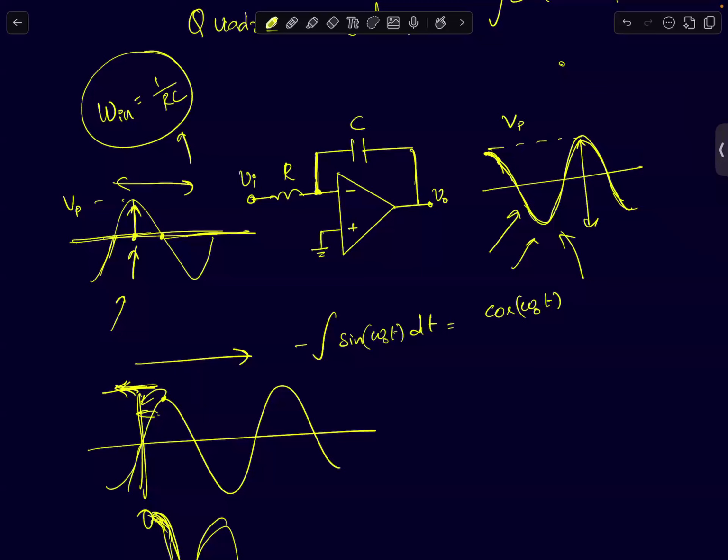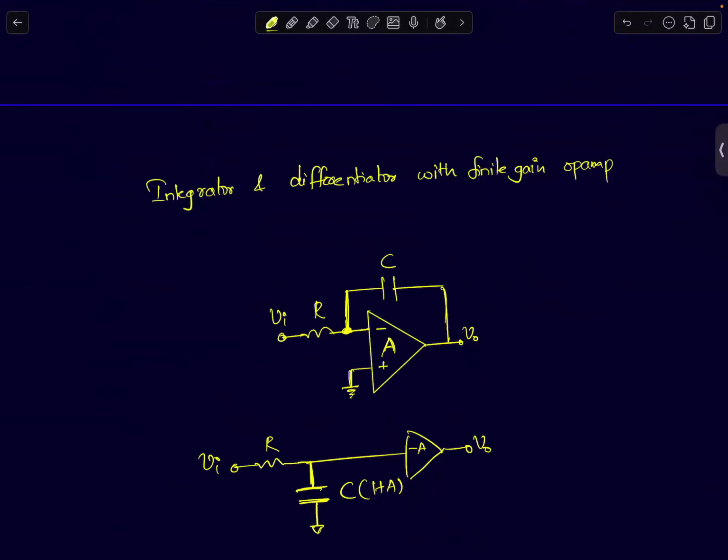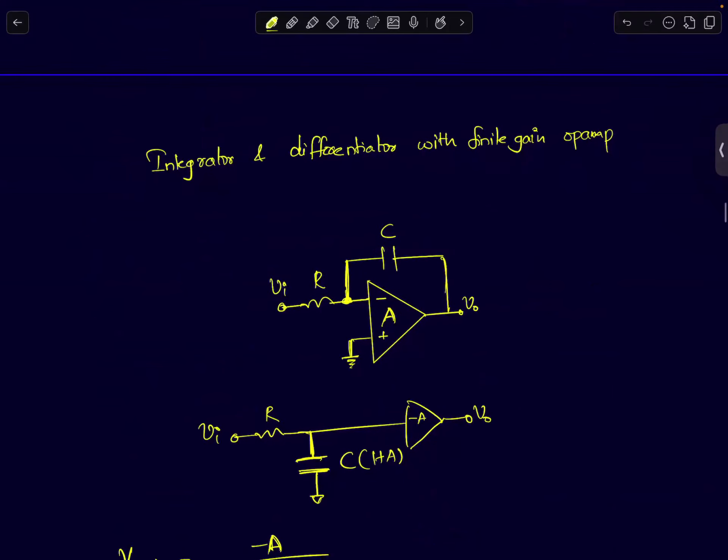The systems that we use today operate at much higher frequencies, so an op-amp circuit may not work, but the idea is somewhat like that. You can think of it like that. So if I feed it a sinusoid, I'm going to get a cosine waveform. And at a later time in the course, we will see that there are such circuits called quadrature oscillators. We will build some oscillator circuits where we exploit this very simple principle where we feed sine and get cosine at the output. That's it. So, the next step, let me just